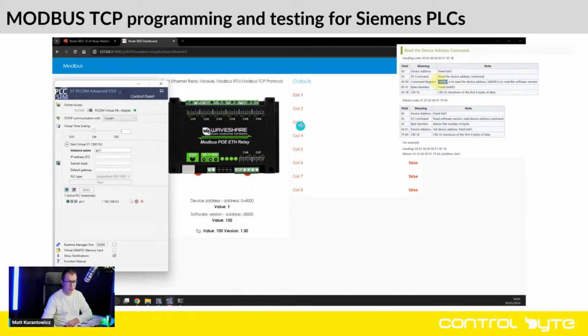We can control such a device using Modbus TCP or RTU, and this is a Modbus slave. If you want to communicate with such a device, you need to use a master device. You can use Finder Opta or Siemens or Codesys, okay? This is only remote I/O using Modbus, but this is a slave device. In our course, we will simulate such a device in Node-RED, but we'll launch such a course next year.